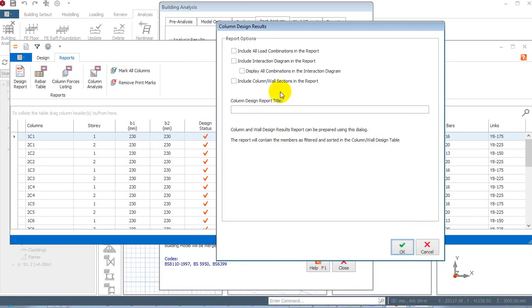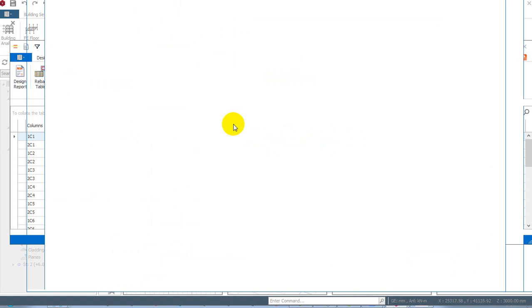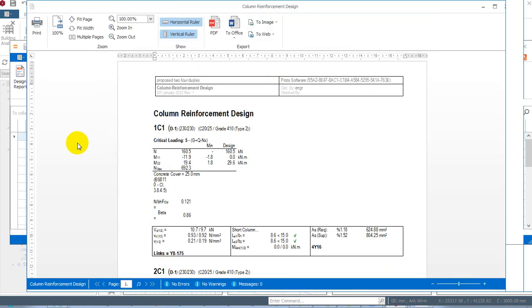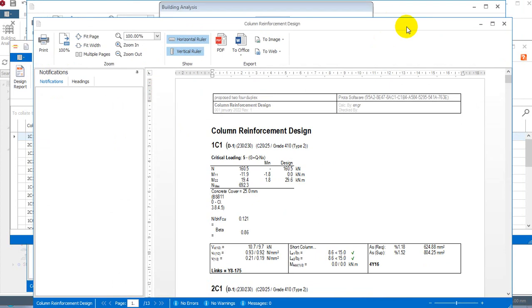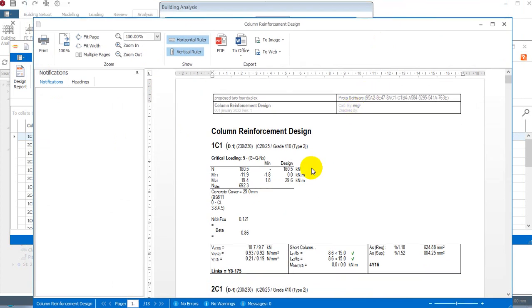Okay, now you can see this design status, the colors have actually changed. What this means is not up to date. To make this turn green, I have to go back there and rerun the analysis again. So that is why those colors have changed. But you can see that indication is not a red indication. It's not telling you that it has failed. It has just changed.